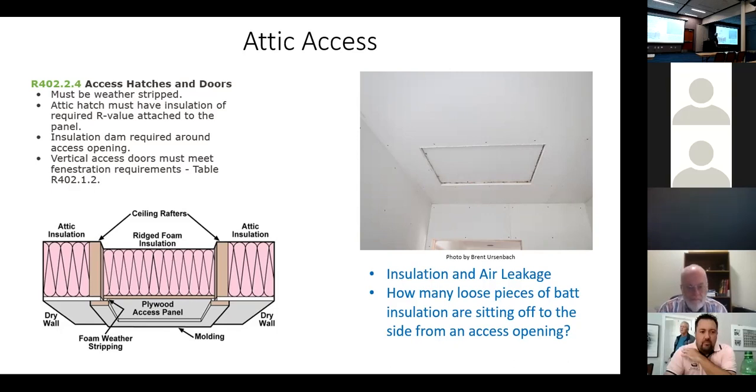But it's one little thing that actually makes a big difference. I don't know if I put it in here simply because of the size. Doesn't like the look of it. You just have to tell them how much energy they lose. I have some thermal images, I've taken them with my FLIR camera, and it's just crazy, the heat loss and the heat gain that occurs through those access panels, where all you have is a piece of 1/2-inch drywall that isn't sealed, and it's up at the top.